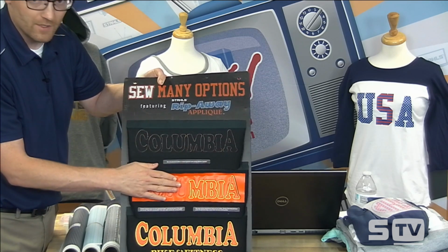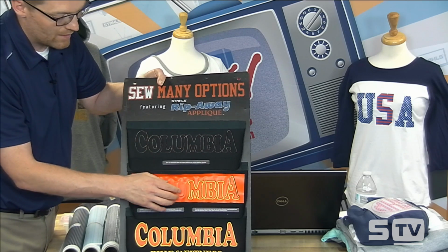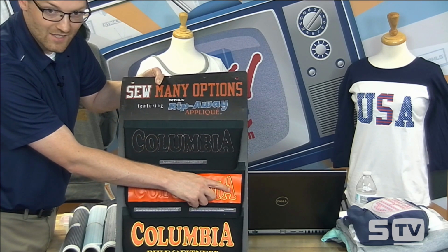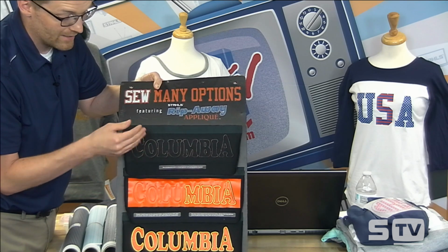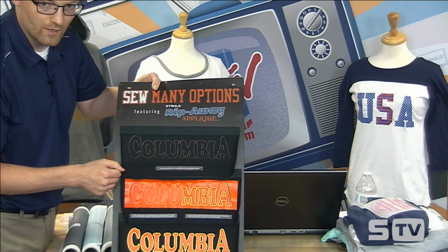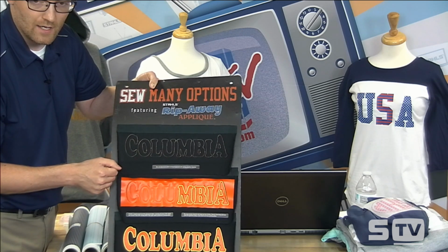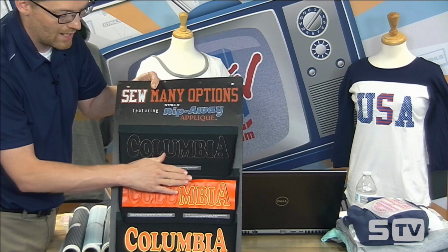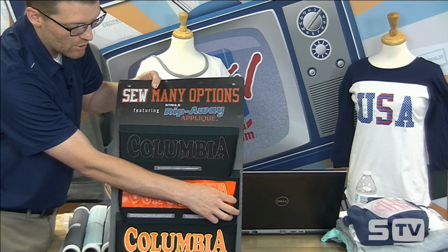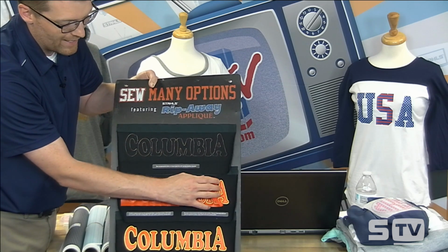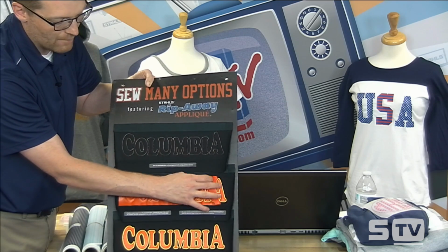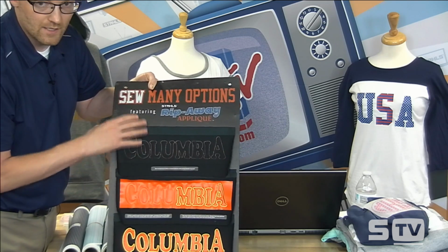Lay it down over top of this placement stitch. Then you basically sew out a satin stitch, which perforates the edge of the heat transfer vinyl, basically cutting it for you instead of having to run it through a vinyl cutter like traditional applique work, saving you a lot of time with layout. You just lay out a sheet, sew a satin stitch, and then you tear away the excess. You rip it away, just basically leaving the applique fill, the pattern fill inside of your design.